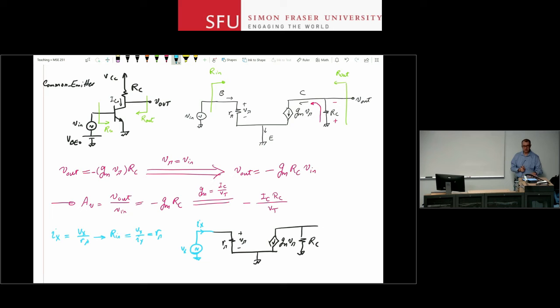I have calculations at the top for the gain for V in. I could have used those calculations to calculate R in as well, as long as my V in, the input source, doesn't have a series resistance, for example, right? Because all I did for the second part is that I removed V in from the top part, put another V that essentially is the same in a small signal source in its place. I could have saved myself a little bit of time, but nonetheless, this is the procedure.